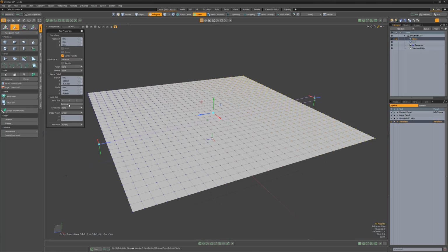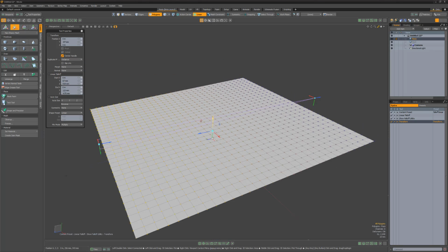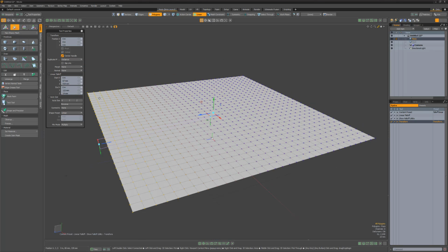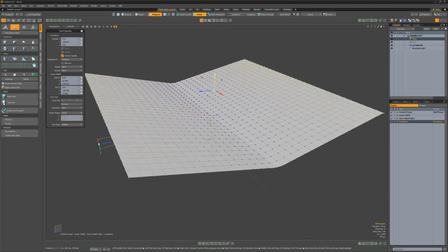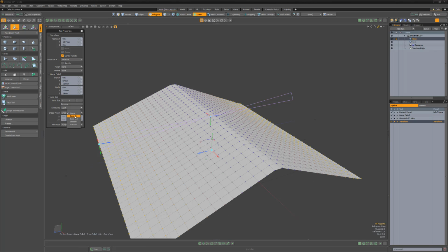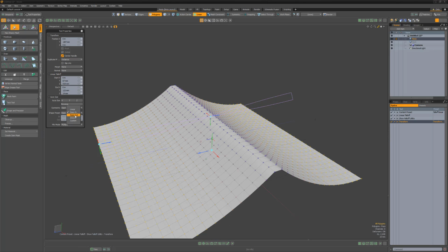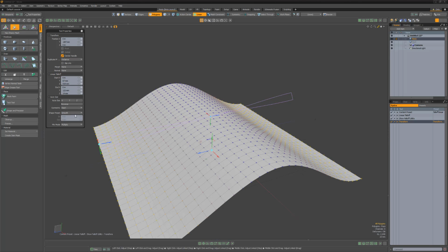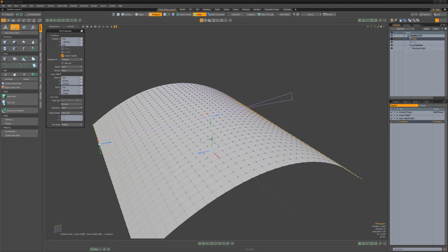You can quickly reverse the influence of the falloff by using the reverse option. The symmetric options enable you to mirror the influence area of the falloff. You can also change the shape of the falloff by taking advantage of the shape presets, which are similar to modifying the interpolation of one key to another in the graph editor.